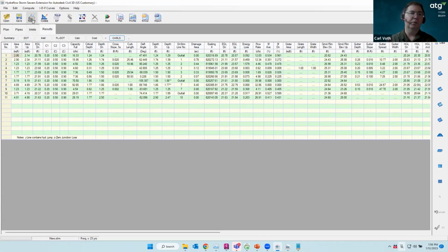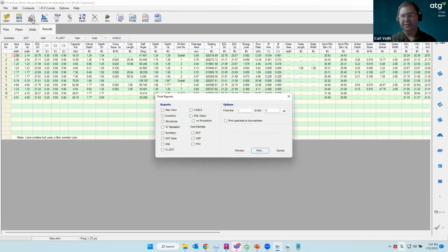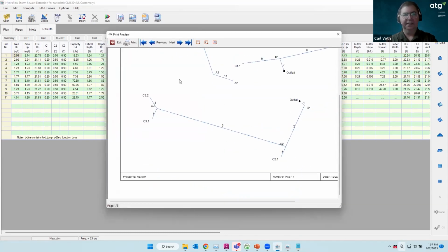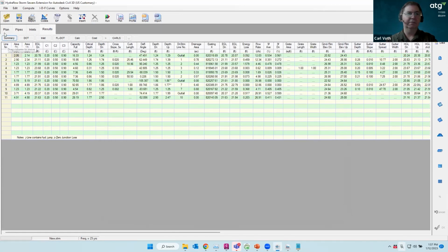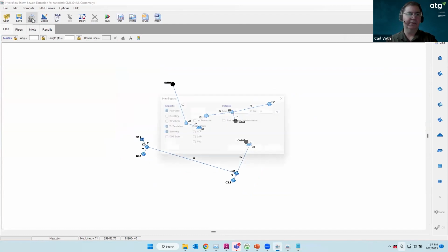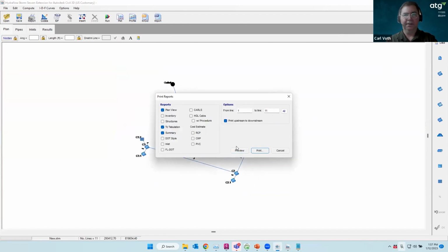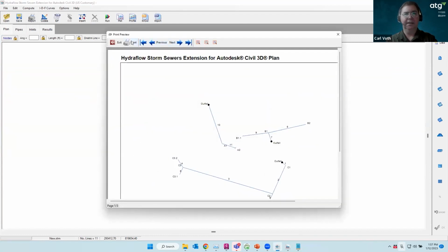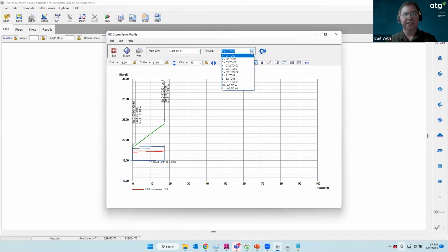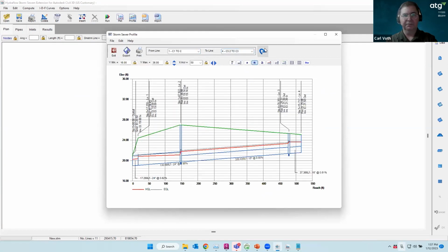All right, with that report being done, since we only have 3 minutes left, I'm going to show you this. And then right through here, all of these fit in here. If they do not fit in here, what you need to do is go back and go to plan, minimize about twice, hit report, and then double check. And now your pipe report is taken care of there. If you need profile information, you can double check and see if everything is flowing properly.